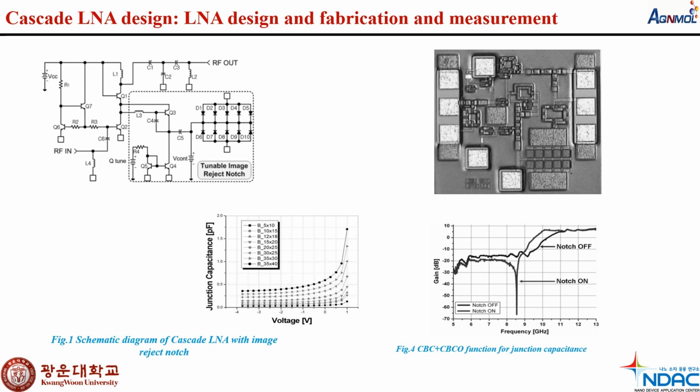Furthermore, noise figure variation between 0.2 decibel to 4.8 decibel, and small gain variation of 1.2 decibel to 1.6 decibel between notch off and on states. And this is about the fabrication method and the testing method of this LNA chip.